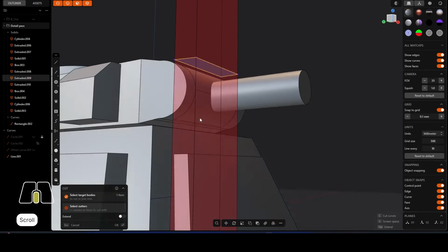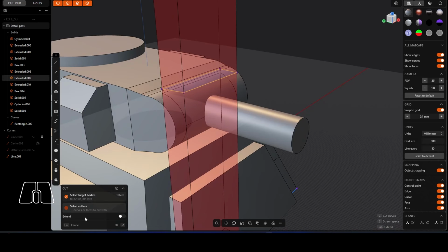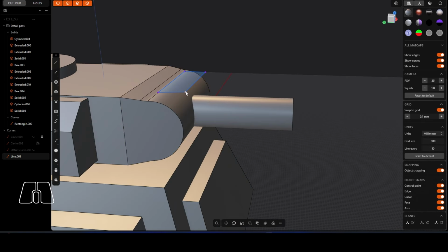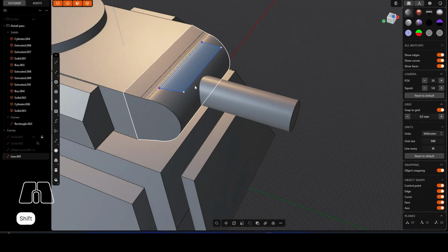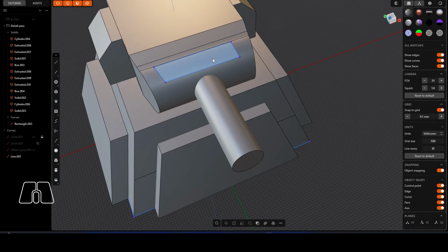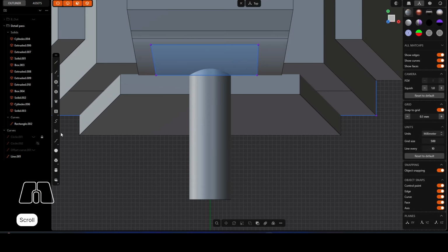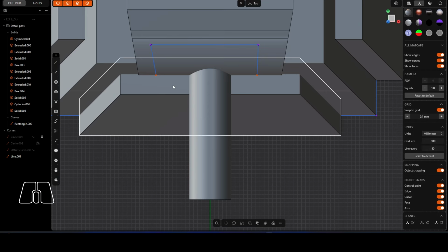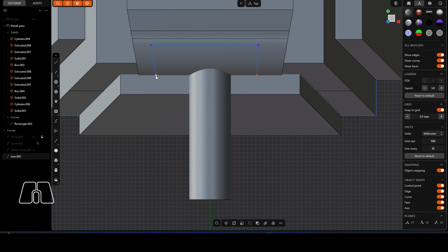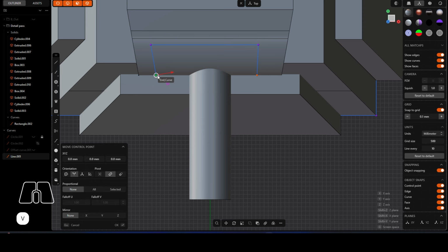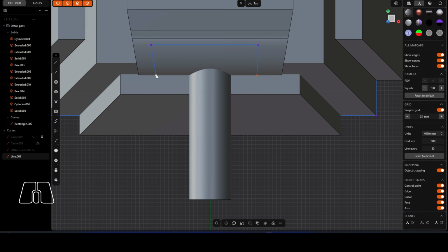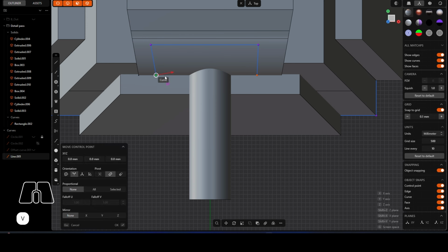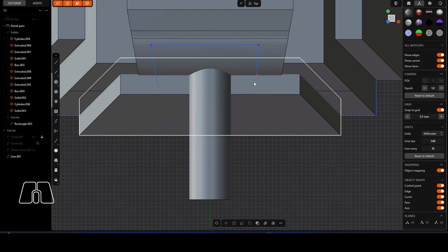So you can see there, as it cut all the way through, I don't know whether that line there is just this. So what I might need to do is just grab this section here. So what I'll do is, in fact, I'll just trim this again. Let's trim that down. I'll grab this piece here. Let's use GV. Grab that. So it should, whoops, G and then V. There we go. And we should be able to just move that just to make sure it doesn't overlap there.